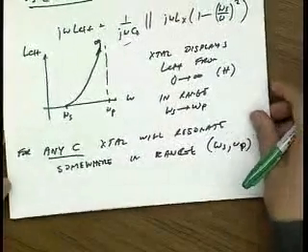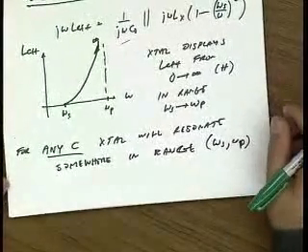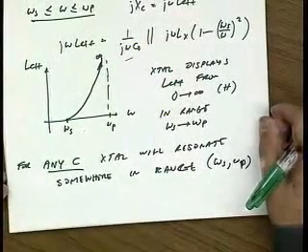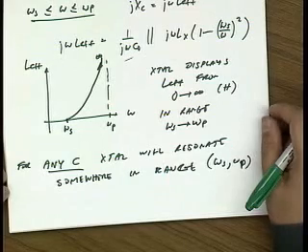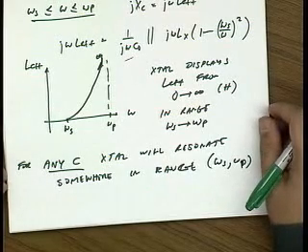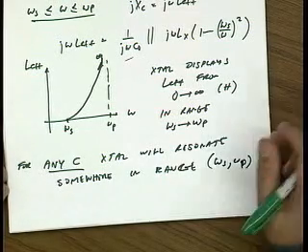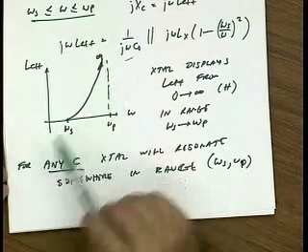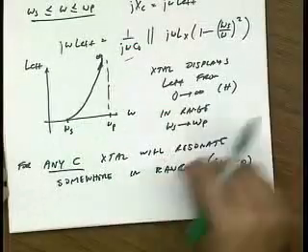Now, question. So what about the, I mean, I have different values of L depending on which frequency I resonate. But what about the Q of the resonant circuit then across the whole range? Well, this is an extremely small range of frequencies, so the quality factor changes very little in this range.